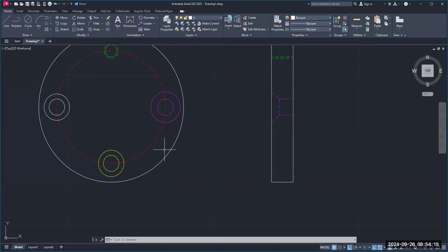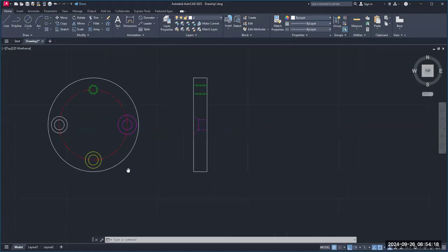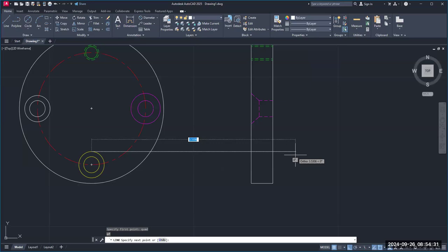All right, now this is a spot face hole. Guess what? We're going to go back to what we did before. We're going to go to line, type in quad, enter, and I'm going to snap at that point. And then come over here and click, enter. I'm going to show you something else you didn't know. If I enter again here, I'm in that mode still. All I can do is type in quad. Click, drag it over, click, enter, enter again. Now it makes it much easier.